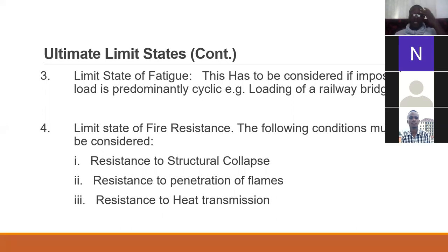When they were bombarded, flames were generated, and these caused heat transmission to the steel elements. That heat causes steel to yield, and after yield they lose their strength. Subject to that, the whole buildings failed abruptly.